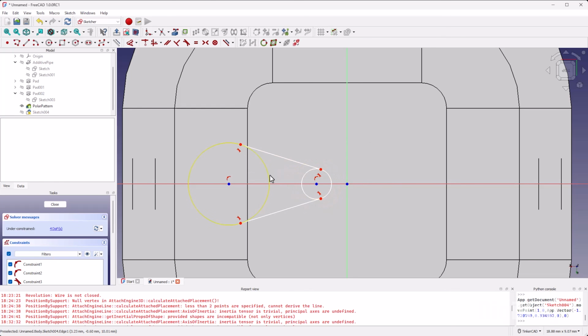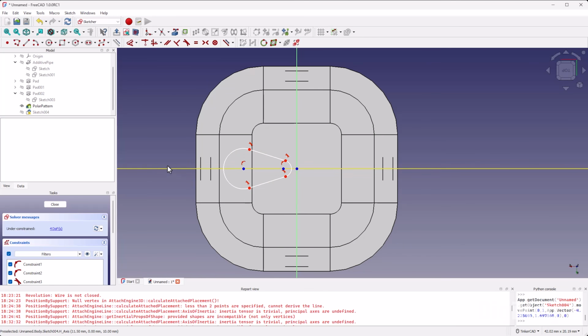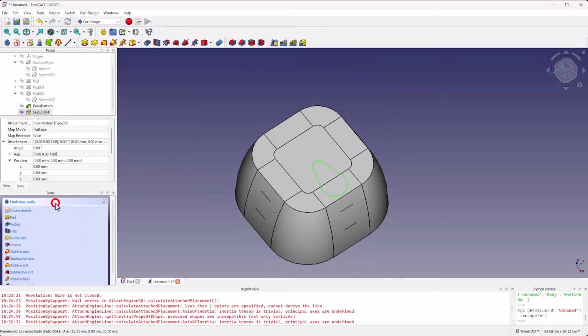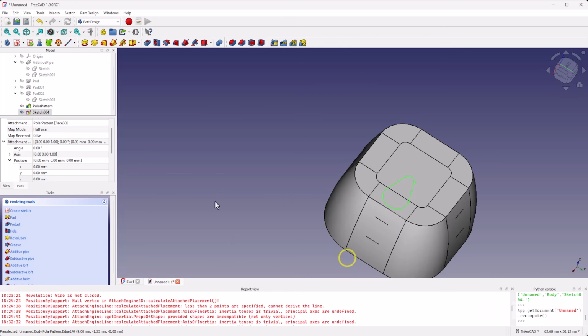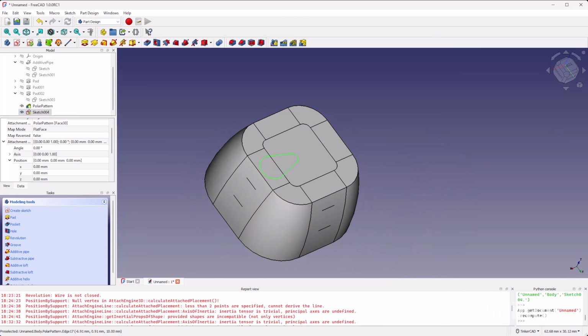But you notice we've got these internal circle arcs. This trim edge tool is really useful for stuff like this. We could just click that and it removes that arc that's internal. And now we've got that teardrop shape. And I'm going to make it a little bit bigger. Oops. Bring it up. And I'm not going to even fully constrain this because this is kind of a creative endeavor that we're doing here. Click close, and that's the start of the little teardrops that we're making.